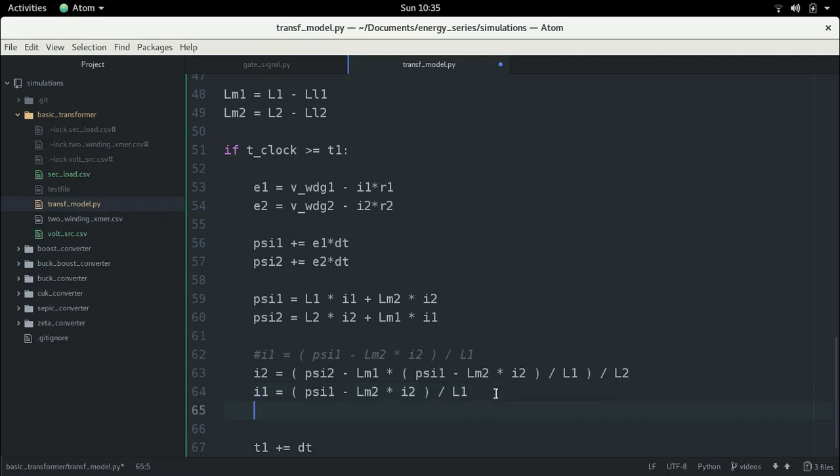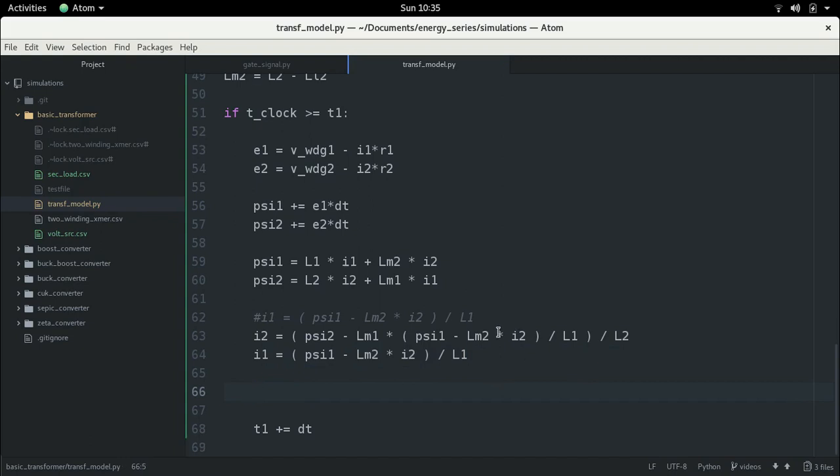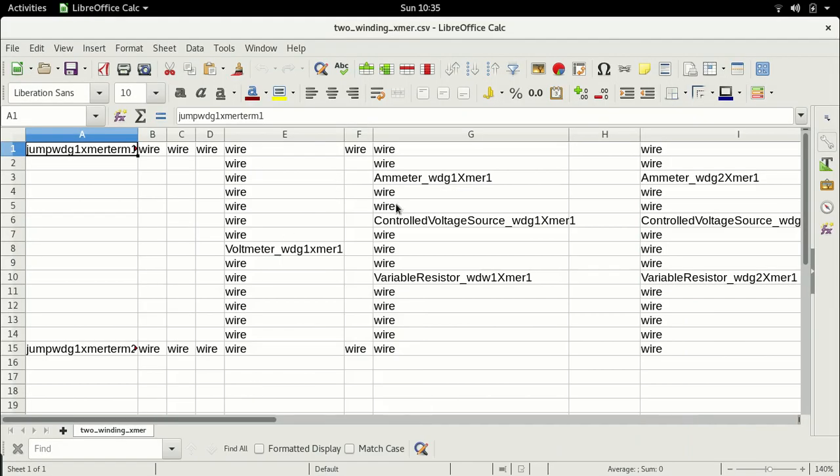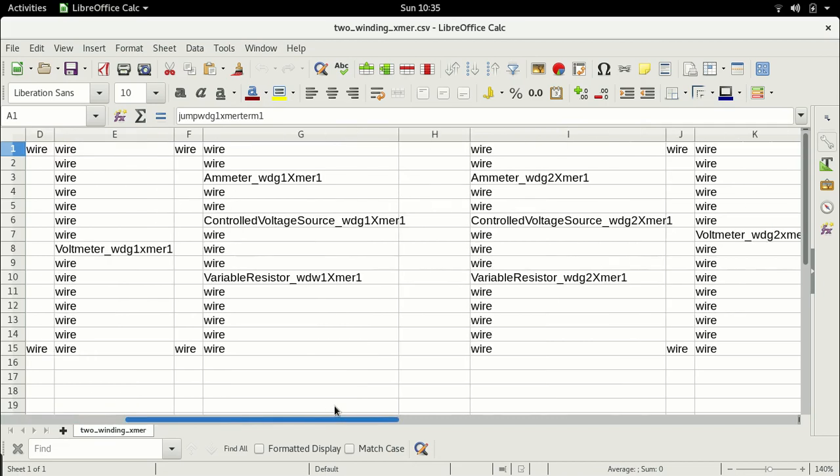Now that we have these two, I1, I2, the next question is, this has to be now placed back into the circuit, right? So now that we have the currents that flow through these windings, just a recap, we are applying a voltage. It could be to just one winding, either the primary or the secondary, or we could have voltages applied to both windings. Doesn't matter, right? In a transformer, anything can happen.